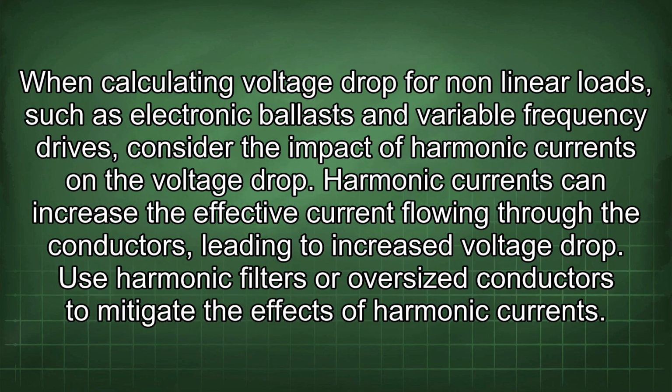When calculating voltage drop for nonlinear loads such as electronic ballasts and variable frequency drives, consider the impact of harmonic currents on the voltage drop. Harmonic currents can increase the effective current flowing through the conductors, leading to increased voltage drop. Use harmonic filters or oversized conductors to mitigate the effects of harmonic currents.